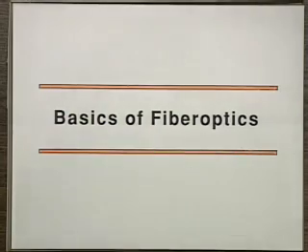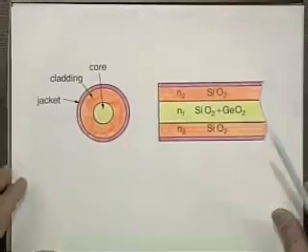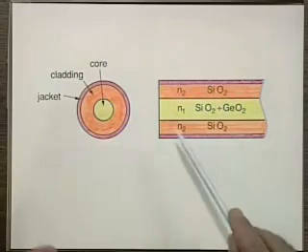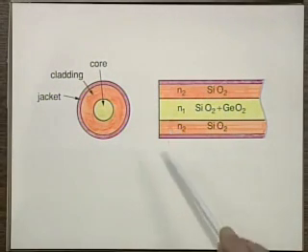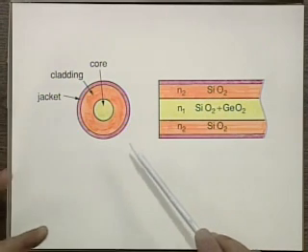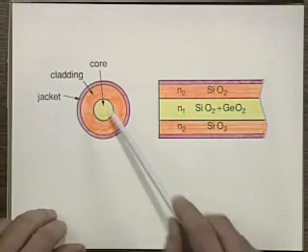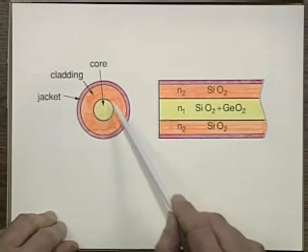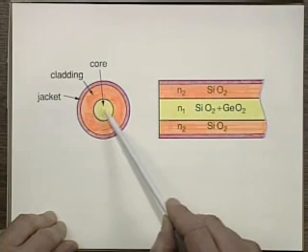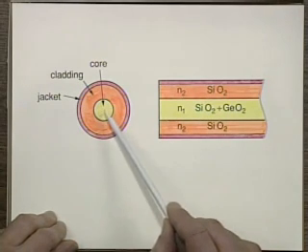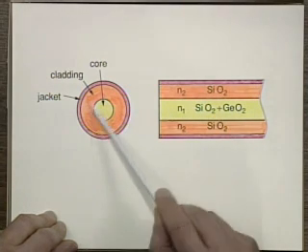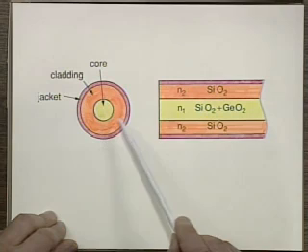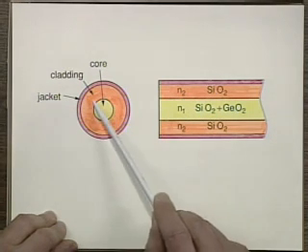So the first question one asks, well, what's a fiber? Now, fibers have been developed for many years, way before lasers, and they basically look like this. If you look from the end, they have a core, which is one type of glass of a certain index, let's say index N1, and surrounded by another glass of index N2 called the cladding.